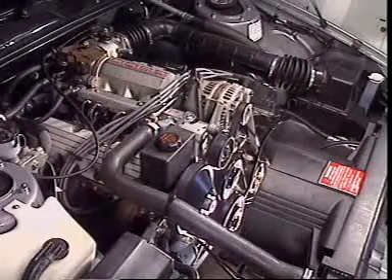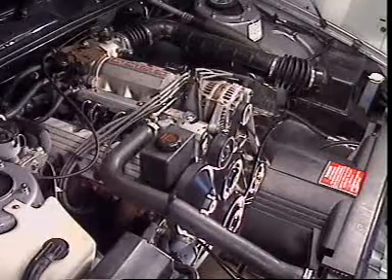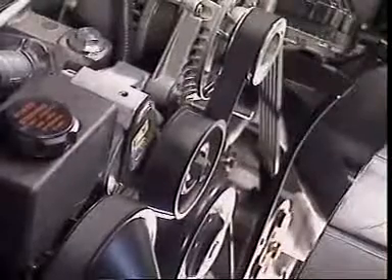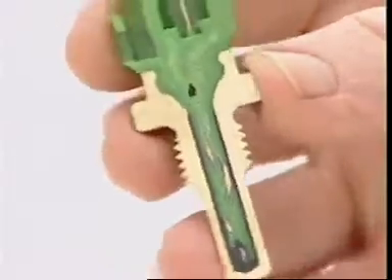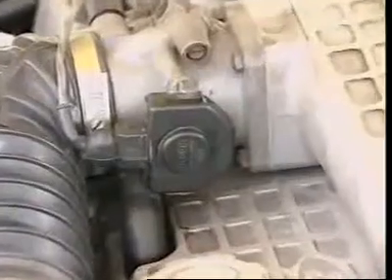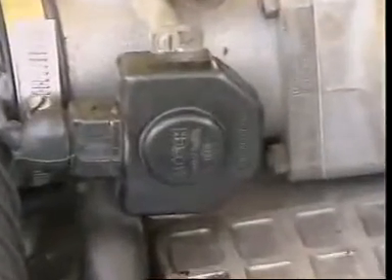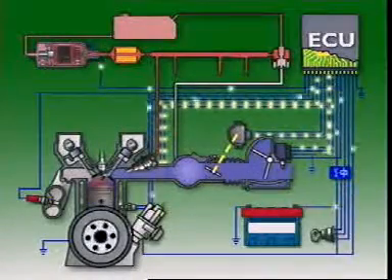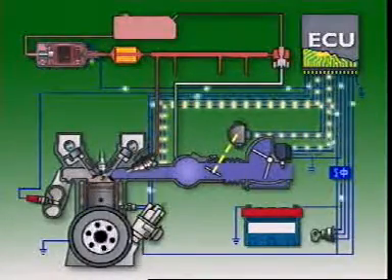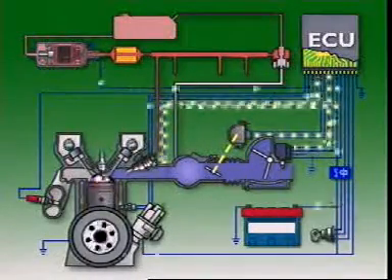A basic EFI system needs input signals on ignition switch operation, engine cranking, the amount of air entering the engine, coolant temperature, throttle position and engine speed, and battery voltage. The varying data received from all of these inputs allows the ECU to arrive at its injection setting.